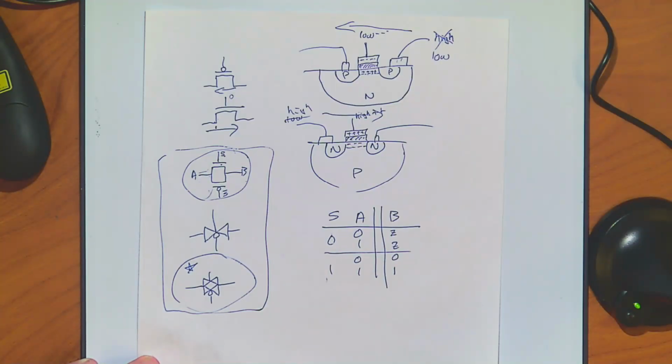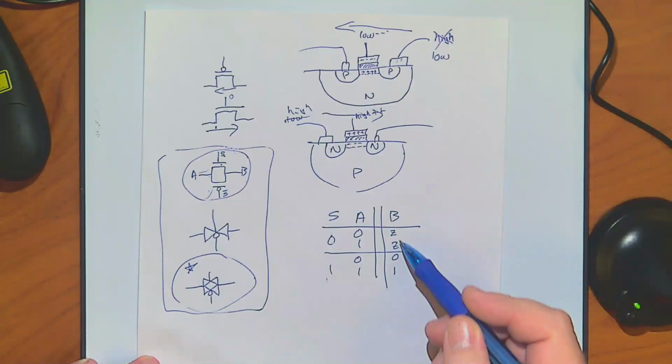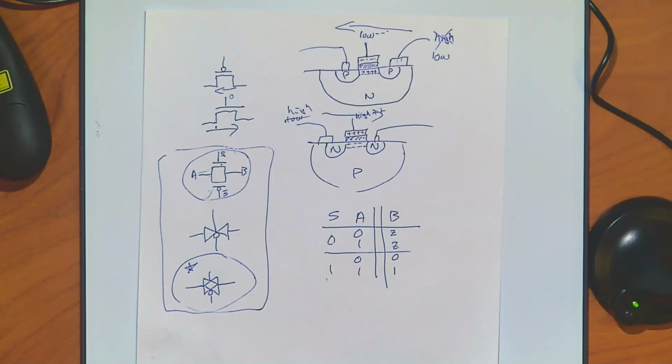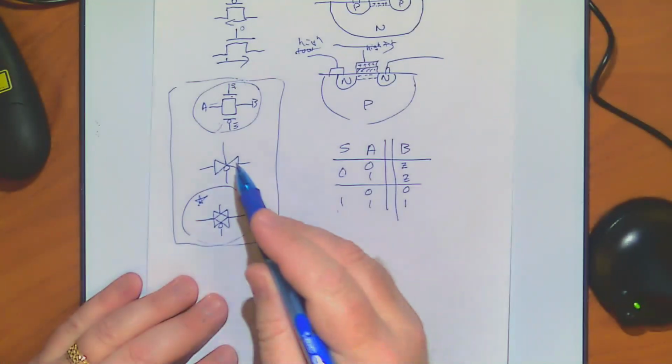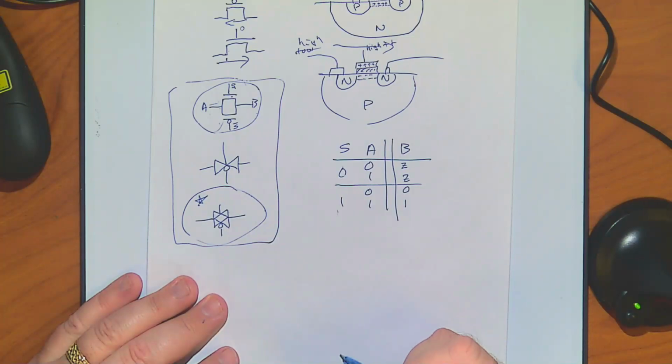So far, so good? So think about this. This setup is basically kind of like the tri-state gates we've talked about, except tri-state gates don't pass things quite as well as this does. Really, this is just an upgraded performance on tri-state gate. And tri-state gates are really good for building muxes. So these should be really good for building muxes. So let's consider our ideal situation, a mux here.